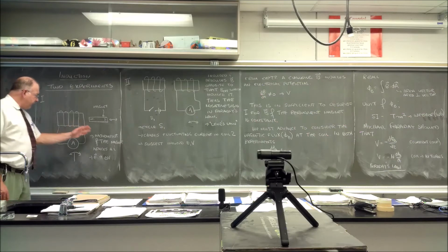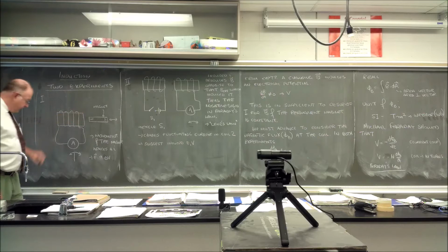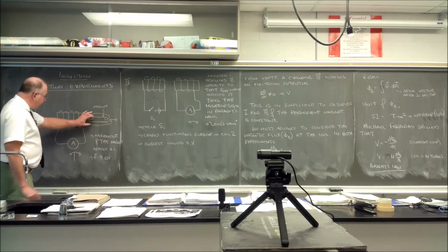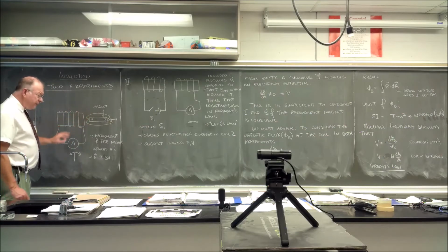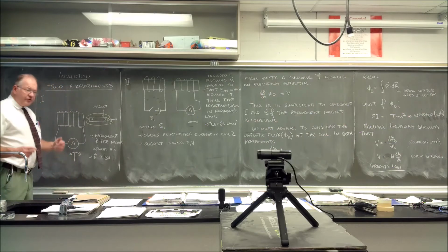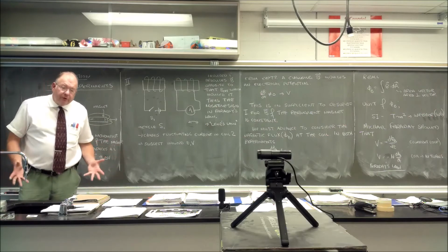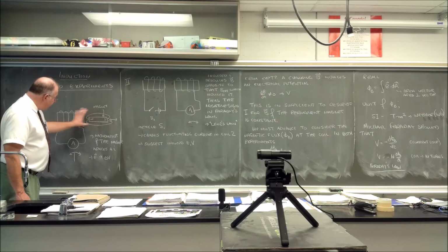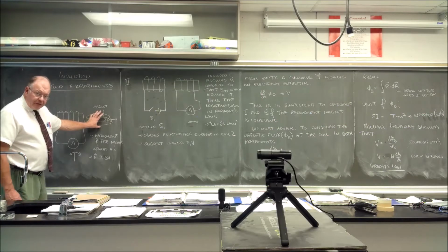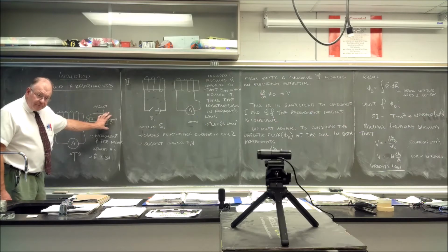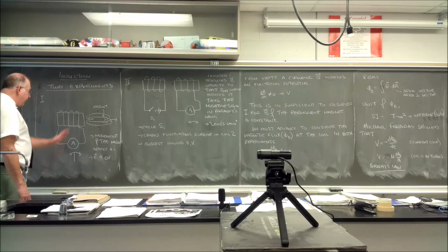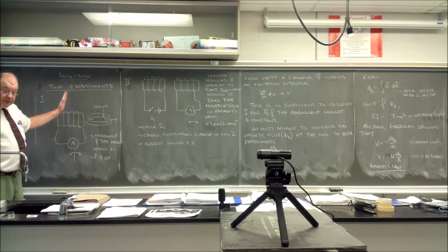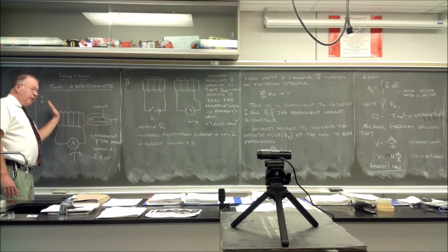But initially, as the flux is growing, okay, remembering that the magnetic field lines do this, right? So when you bring it in, the field lines are getting closer together. So that's going to cause the change in flux to be positive and to be increasing. When the magnet gets to here, at any location, the flux stops increasing and begins to decrease. So initially, your meter is, if it was a galvanometer, something where you have your 0 point in the center. As you bring it in, it's going to go one way.